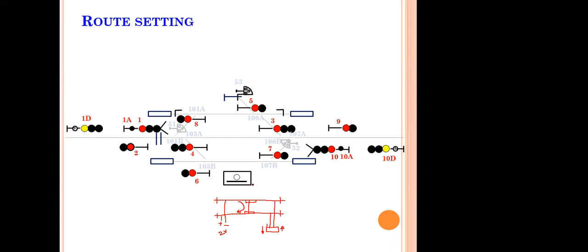Now, this shorting cannot be done by a human being. A human being has a resistance of minimum 25 ohms. So it is not possible by a human being, even if he touches two rails. An insulated push trolley will not short these two rails. A motor trolley, yes, it will short. A train will short. A simple wire is otherwise put here. Yeah, now it's shorted. The track relay will drop. But remember, it is called a fail-safe system. Yesterday, what Mr. Solomon was saying, the system will fail, but it is on the safer side.